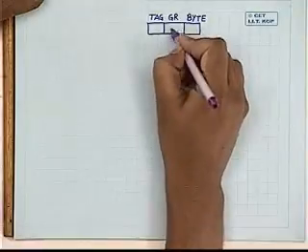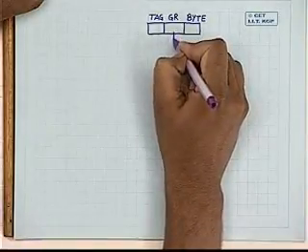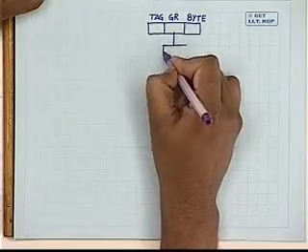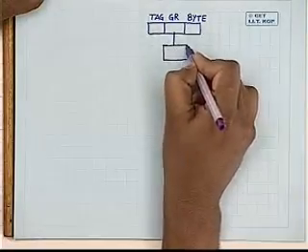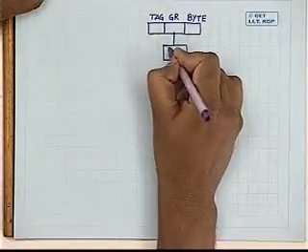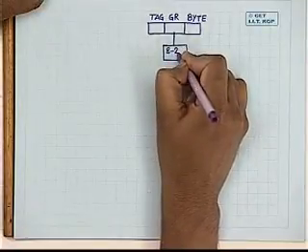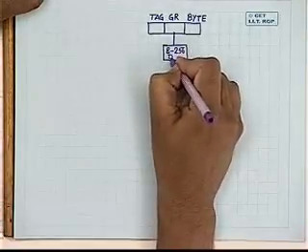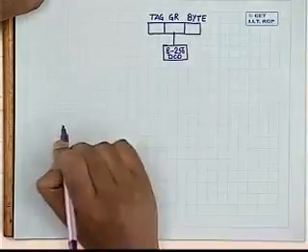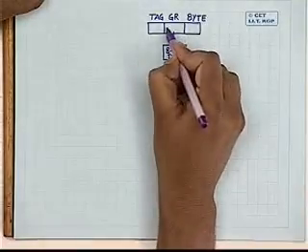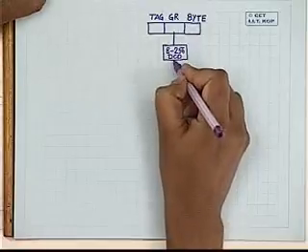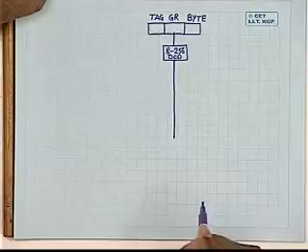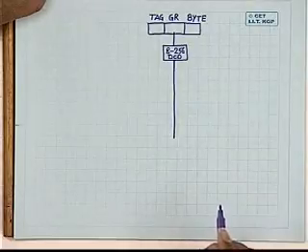Okay. So if I want to identify a particular group, then what I have to do is this group field I have to feed to a decoder. The decoder in this case is an 8 to 256 decoder. Okay. Now depending upon what is the bit pattern in this group field, one of the 256 outputs of the decoder will be high. All other outputs of the decoder will be low.